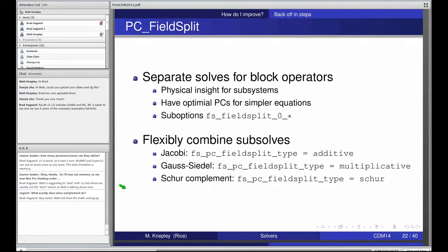So the important preconditioners to be aware of are one, algebraic multigrid, two, the field split option. Why is this? If you set up a purely elastic problem with PyLith, algebraic multigrid will work and everyone will be happy. However, as you probably want to do, you want to put some faults in. And the minute you put a fault in, we do not have a purely elastic problem anymore.